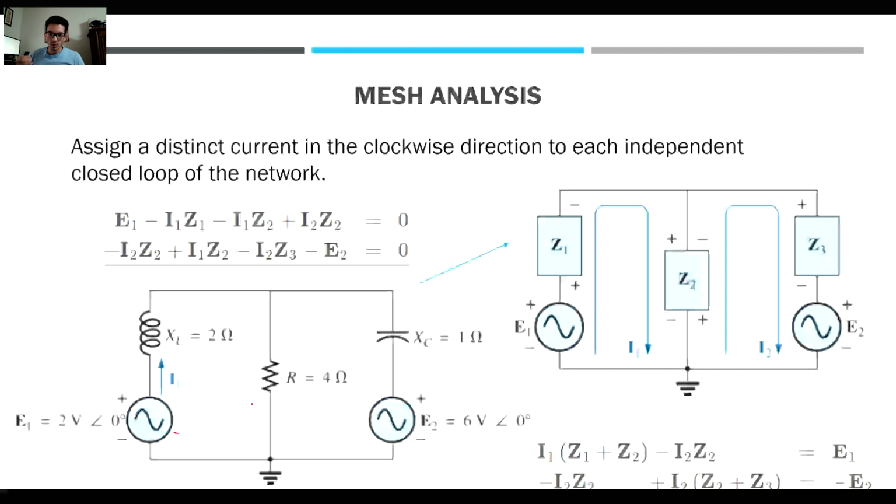If you remember, if you use a multimeter and place the probes at different places of the circuit, if you have a negative sign, it's because the polarity is incorrect. So you just simply switch the probe side and measure the positive part. So the potential difference is the important part. The sign is not as important because it just tells you the direction of the current.